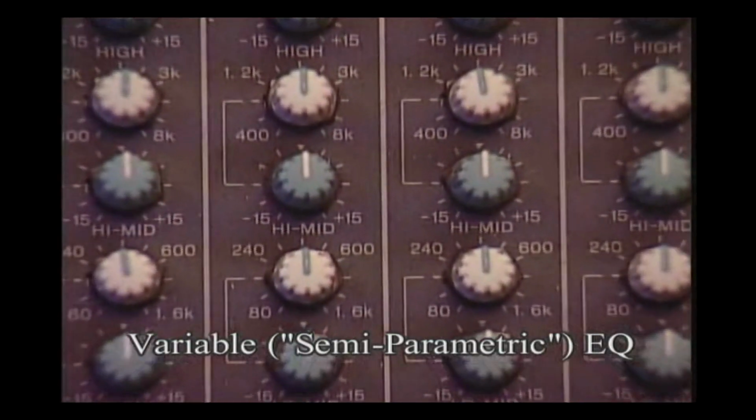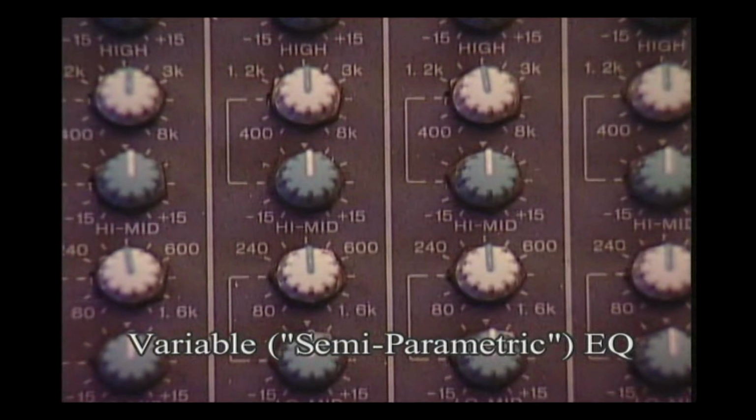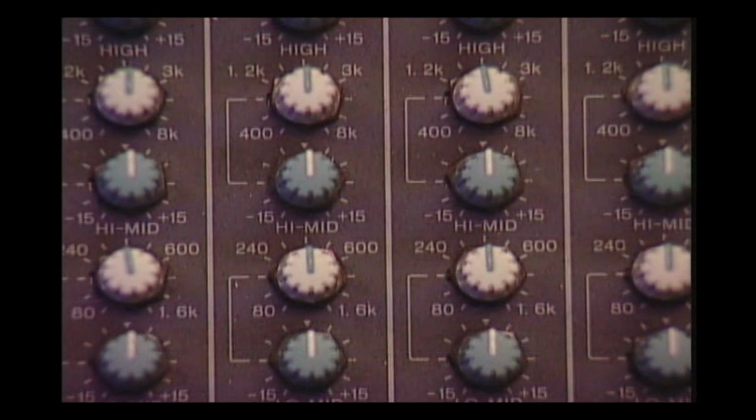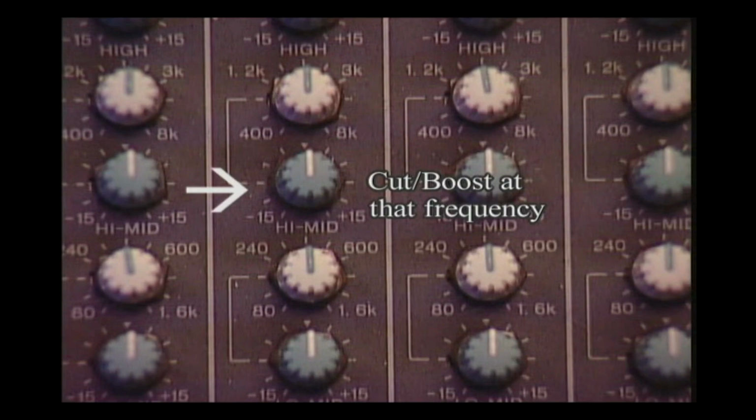From fixed frequency, let's look at variable frequency EQs, sometimes referred to as semi-parametric EQs. Whereas fixed frequency EQs have preset frequency points, variable frequency EQs allow the user to select any frequency point along the continuous frequency range and then cut or boost at that frequency point.